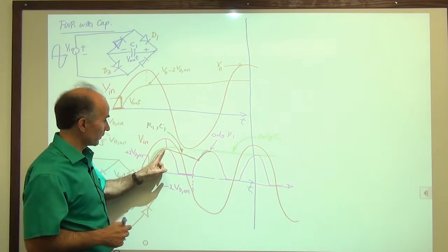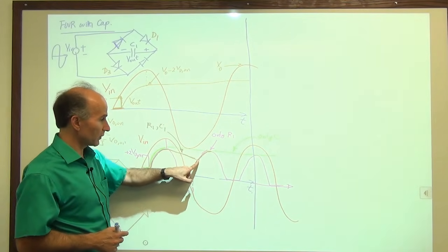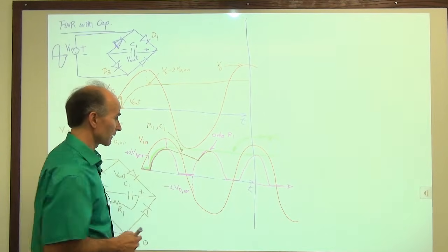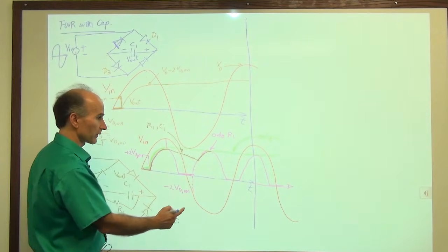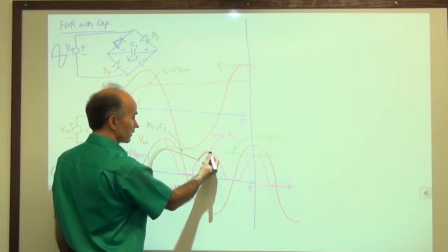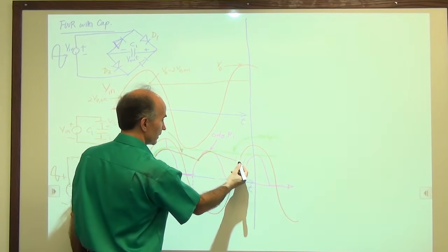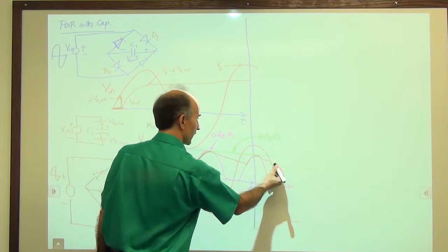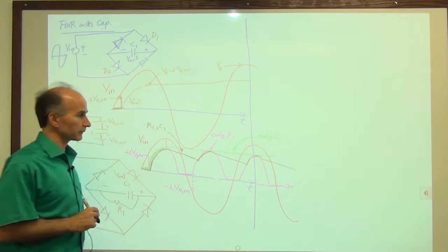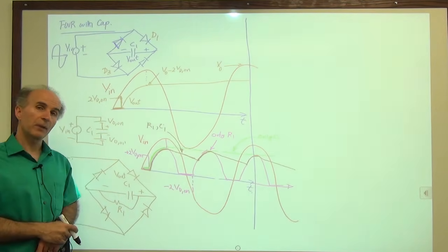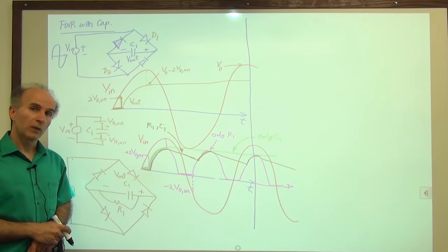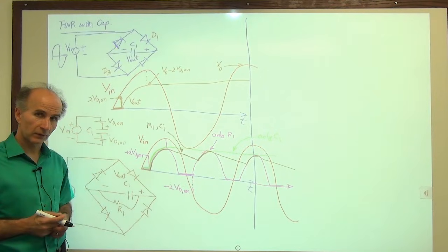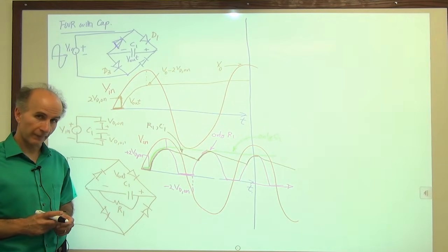So no, as soon as this voltage is equal to this voltage, the 2 diodes turn on again. These are the negative voltages, the other 2 diodes. So we track here, and then we again discharge, and we track here, and then we discharge. So that is the behavior when we have a load that draws some charge from the capacitor when the diodes have turned off.